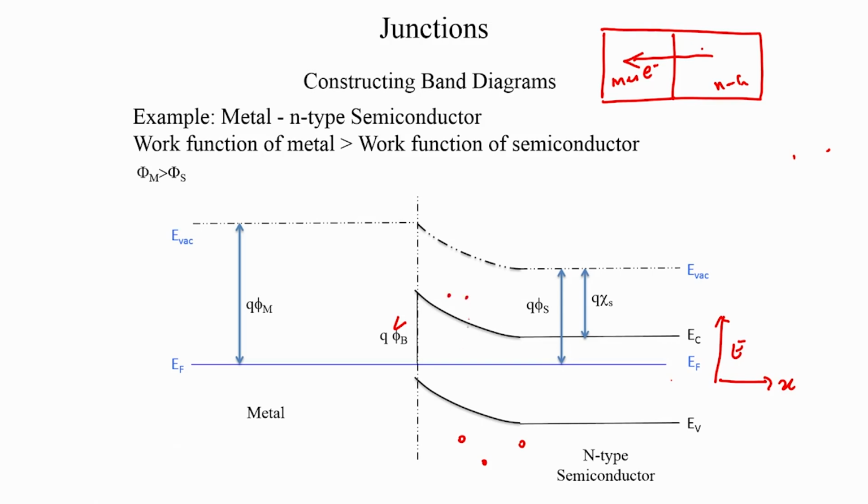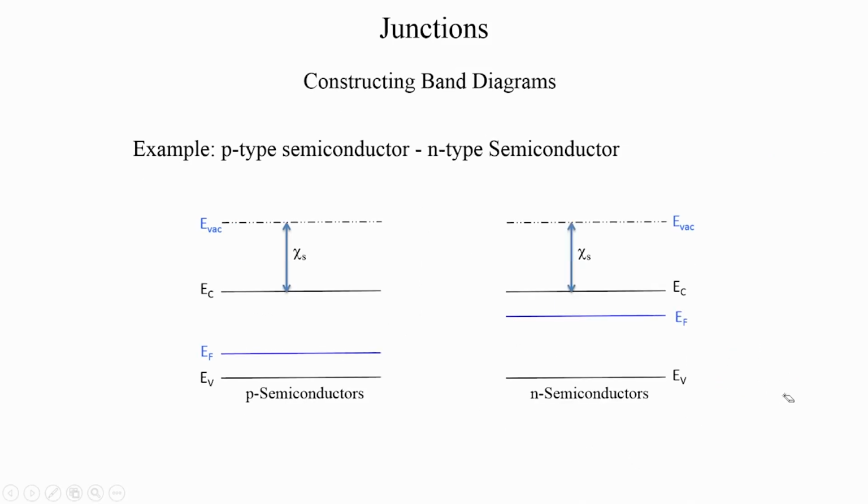So, there are going to be very few electrons here and very few holes here. Therefore, in some sense this junction can be said to be depleted of free carriers. We will come back to these points later. So, this is the way you draw a band bending diagram, and that is the way you look at the different aspects of it.